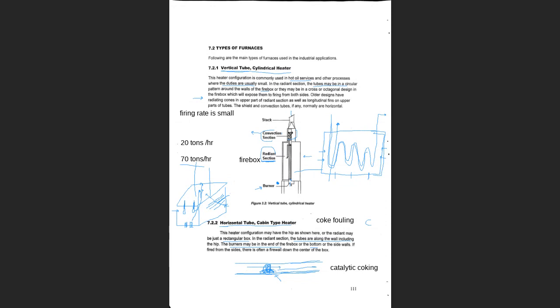يعني you will get one of the coils broken, or fractured coil, and the process fluid will start to flow out, and it flows out in a firebox. فوش تلاحظ إذا مثلا كان عندك فيرنس وكان عندك تيوب مكسور، تلاحظ إن في لهب كبير، عندك نار هنا طالع بسبب إن التيوب إيش؟ انكسر. and the material started to leak from the coil or the tube to the firebox. طبعا immediately once you see this, immediately you will have to shut down the furnace.